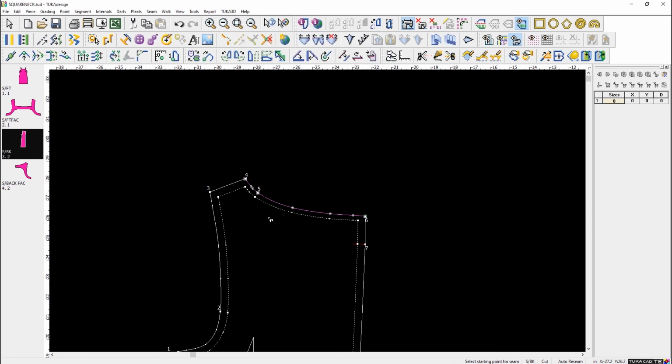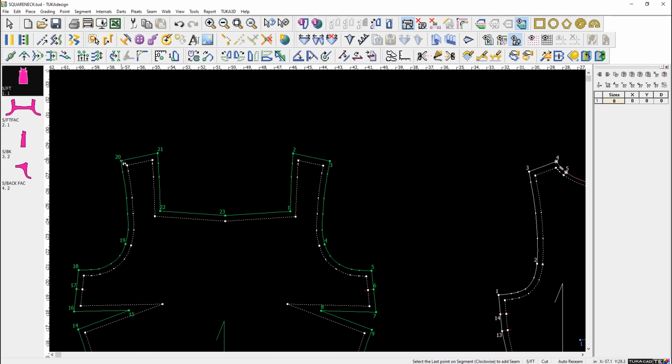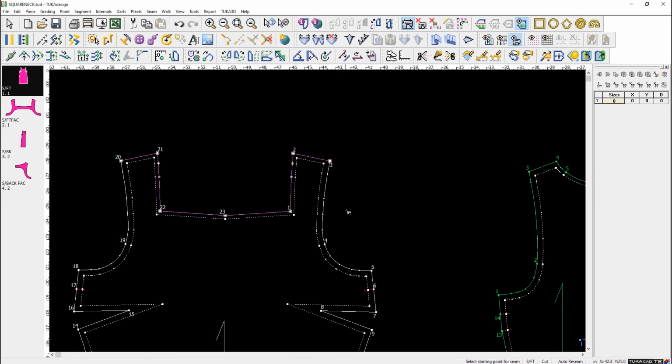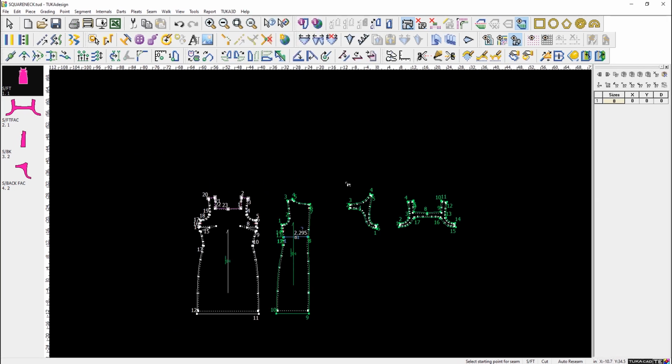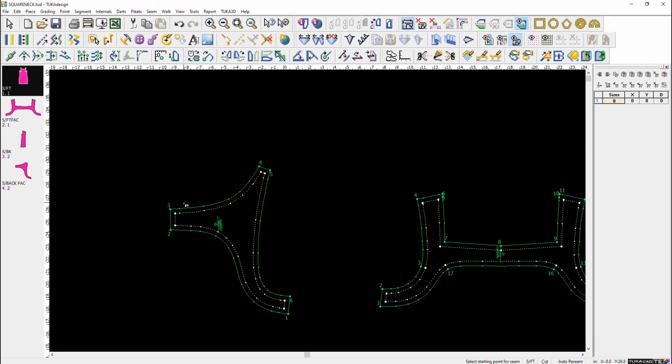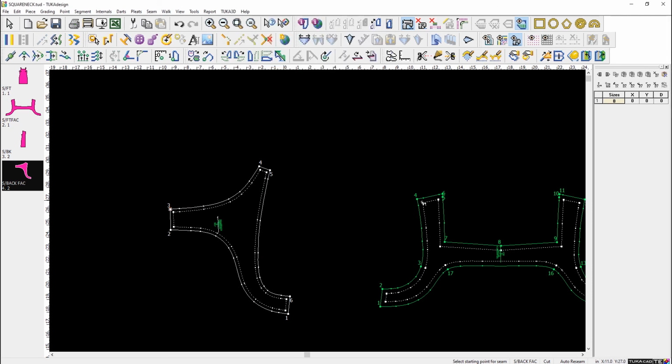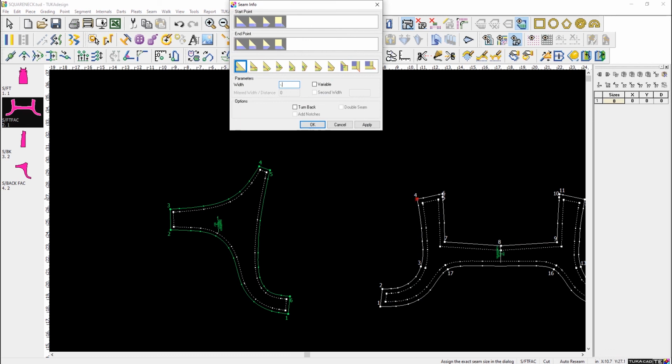So I'm going in there and redefining the sew line. How much? Okay. All right, and then afterwards, when you redefine everything, I think I did all 1/4 inch here, so minus 0.25, and also this one I think I did 1/4 inch, so minus 0.25.